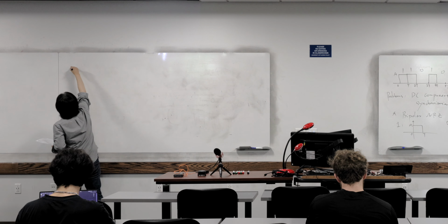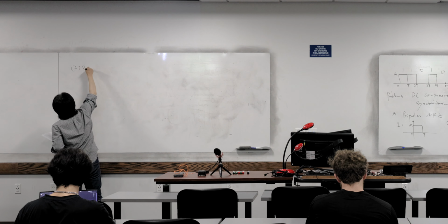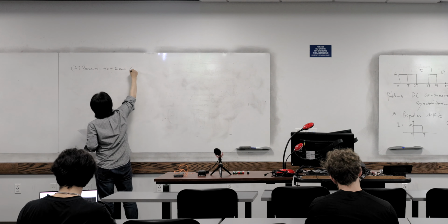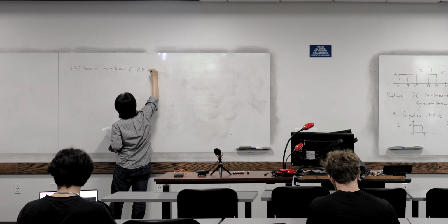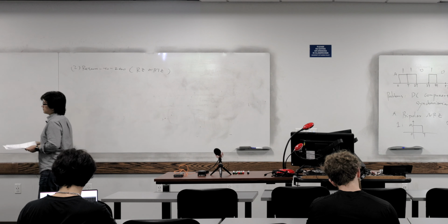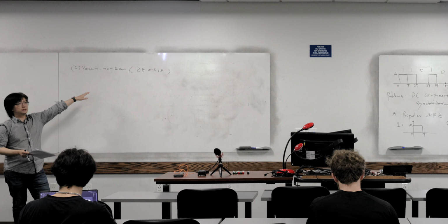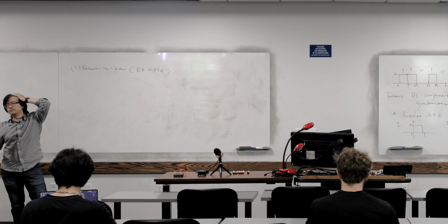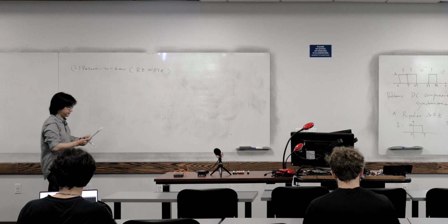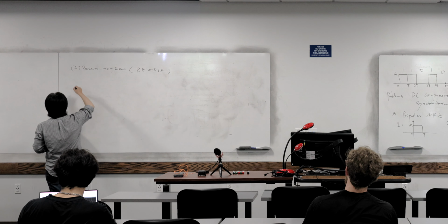Okay, second, return to 0, RZ or RTZ. So for this one, from the name, you can see that it basically means it will return to 0 during the symbol period, right? So again, we have a few cases here.